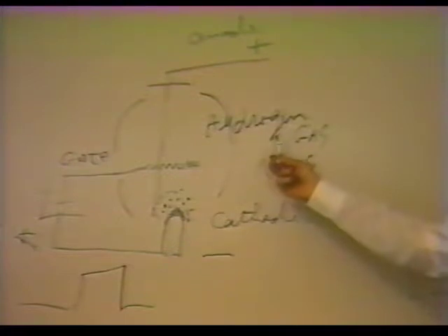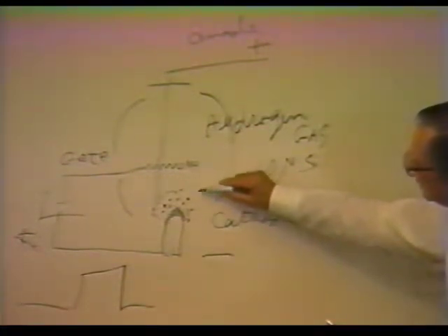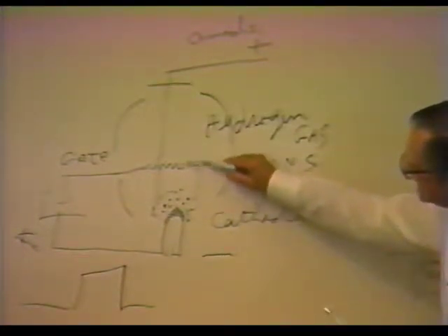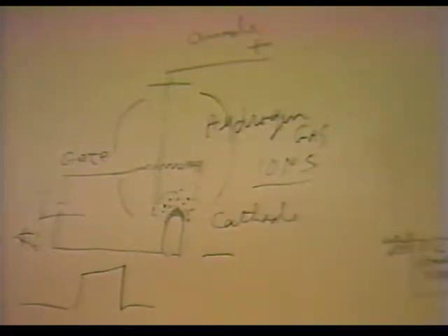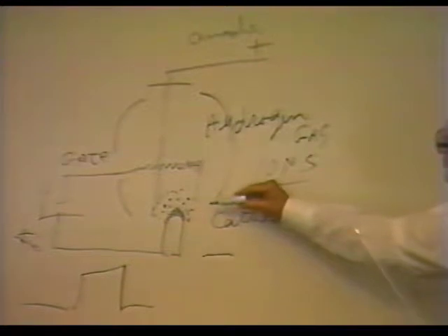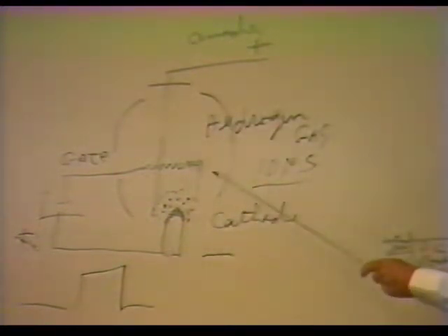Now, what the gas does when it's ionized, just like the gas glows here, is provide a very low path of conduction. So in the old hydrogen thyratron, we had a conductive path, a low resistance path made up of electrons and ions. Now once the tube ionized and went into conduction, the gate had absolutely no control over the device.